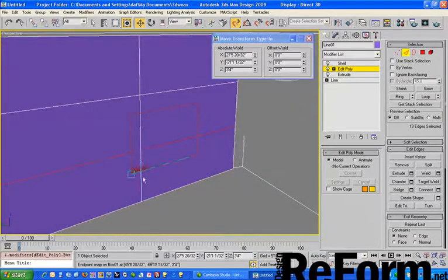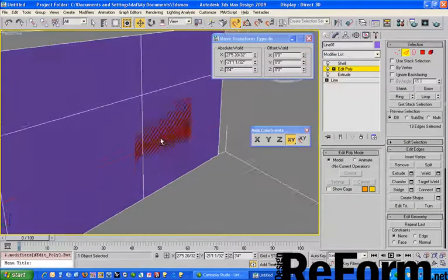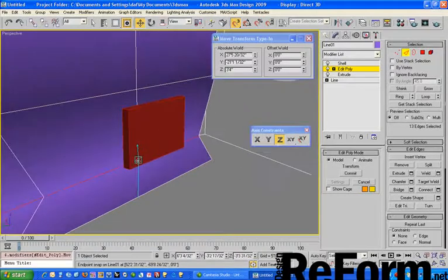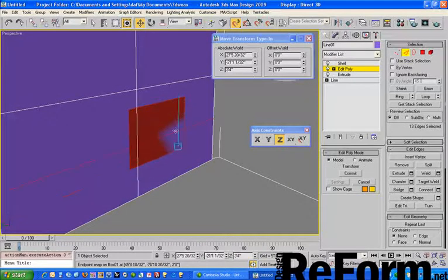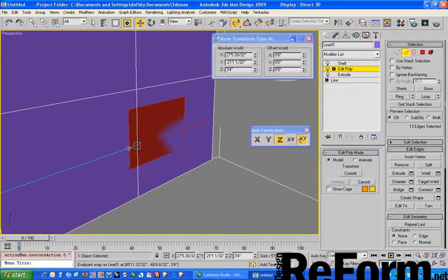And if I wanted to align this bottom face with this top face, I'm going to use my axis constraints and snapping. And they're not up right now, so I'll just right click and bring up my axis constraints. So I want to align this face with the bottom of this. So I'm going to set my alignment in the Z. So now when I can snap that. Let's undo that. And here in my options, use axis constraints. So now I can snap it. See, I'm snapping to that corner, but it's still staying straight. It's only in the Z.